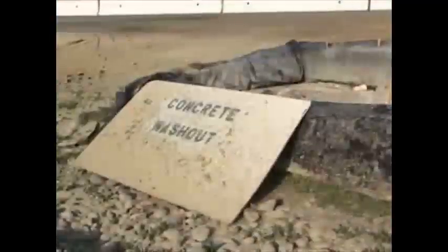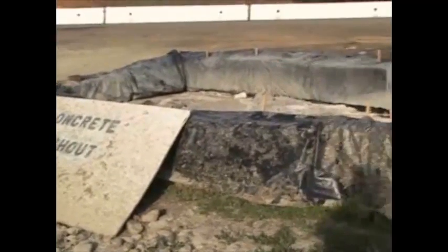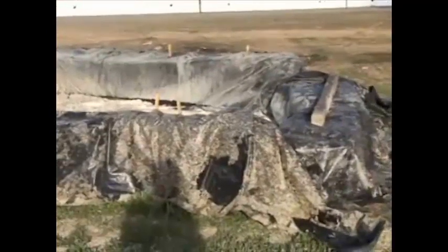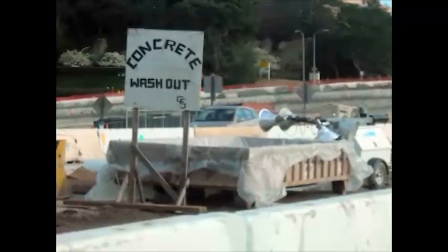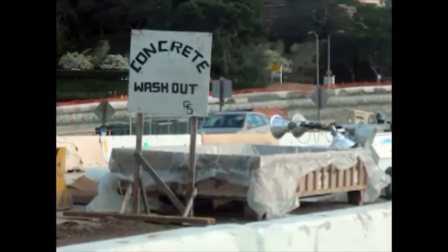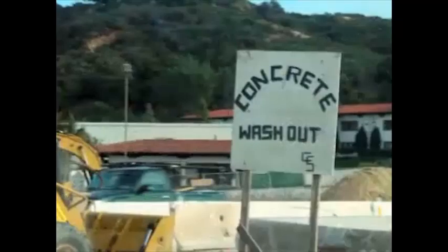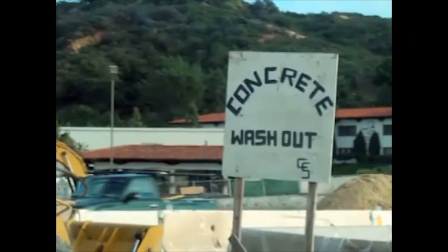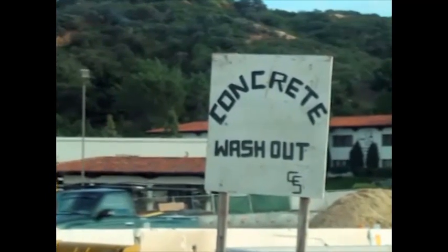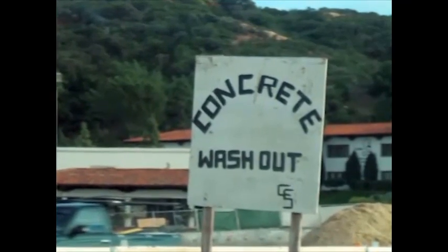A concrete washout sign must be installed within 32 feet and 10 inches of the temporary concrete washout facility. Plywood that has been freshly painted with no less than 2 applications of flat white paint must be used for the concrete washout sign. Sign letters, as indicated on Standard Plan T59, must be stenciled with commercial quality exterior black paint. The testing of paint is not required.